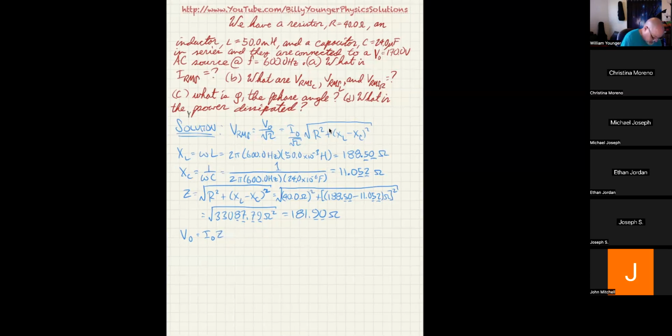I have a question. Yes. What exactly is impedance? Okay, so there's impedance and then there's reactance. Reactance is like resistance in that it has units of ohms. So it does tell us something about how much the voltage will drop across that particular item.